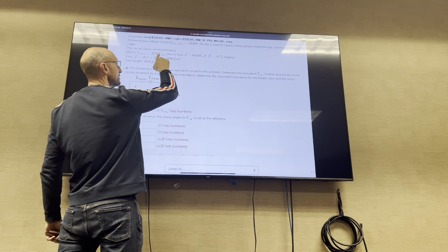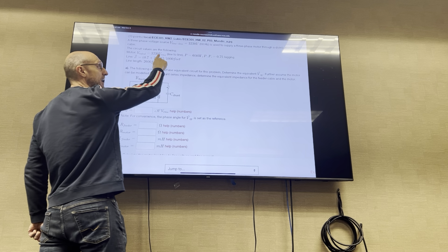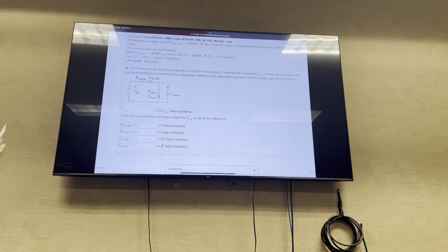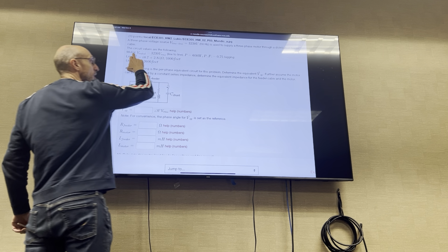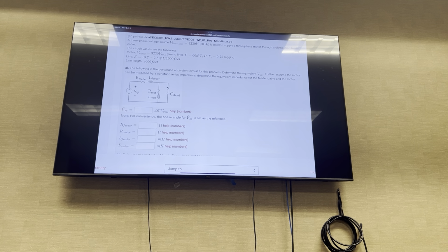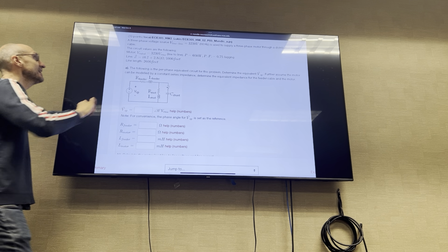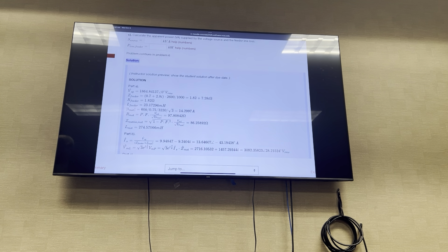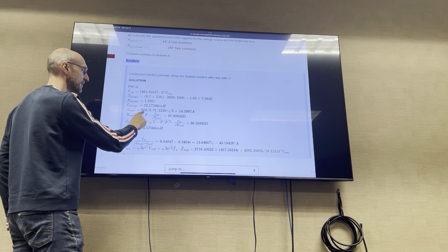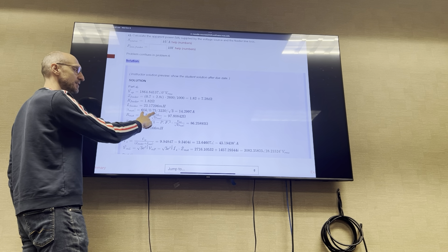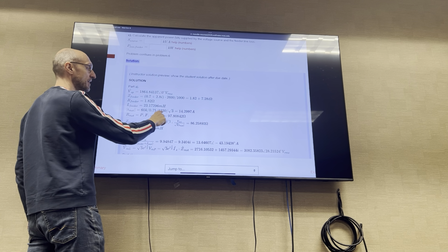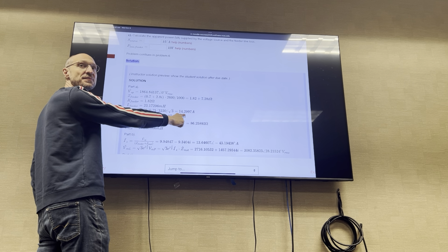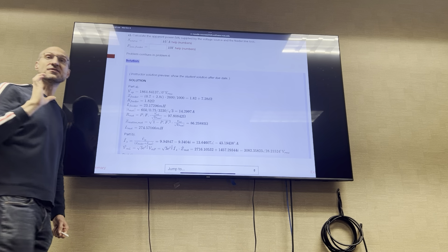This is the power it consumes when the rated voltage is applied, and this is the power factor it operates at its full power. So at the rated operating condition, at the rated voltage, you can calculate the current. We took the rated power divided by the power factor, so that's the S, divided by the voltage, divided by the square root of 3, will give me the line current. Okay, that makes sense. That's the rated value.